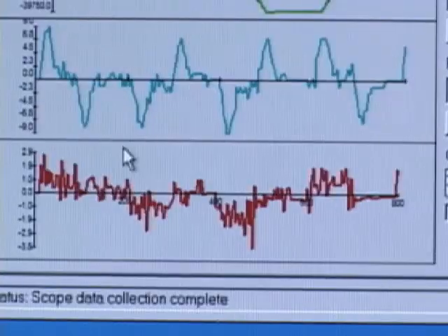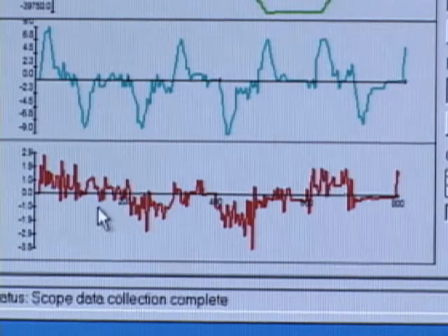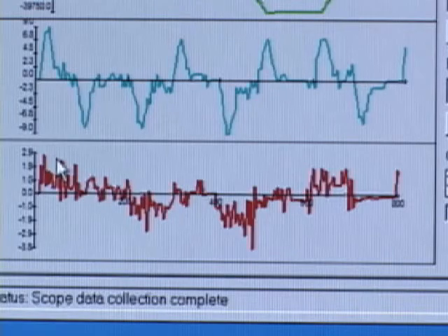Now, the fourth trace shows the analog voltage going to the amplifier. Typically, the range of this voltage would be between plus and minus 10 volts. Here, we're using something within about plus minus 2 volts, which indicates to us right away that the amplifier is sufficiently large and could handle this motion easily. But the significance of this function is in cases that the amplifier is not sufficient.